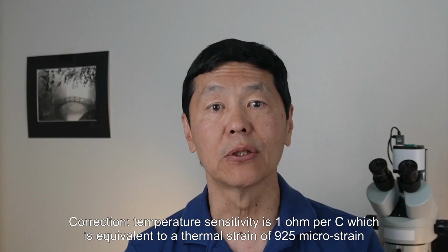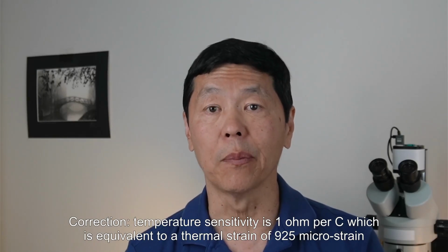This translates to a thermal strain of 3500 microstrain. For comparison, the thermal strain of a self-temperature compensated metal foil strain gauge is about 100 microstrain. Unlike the metal foil strain gauges, there's no way to formulate the silicon to be self-temperature compensating. The only option is to build temperature compensation circuitry outside of a Wheatstone bridge that uses semiconductor strain gauges.